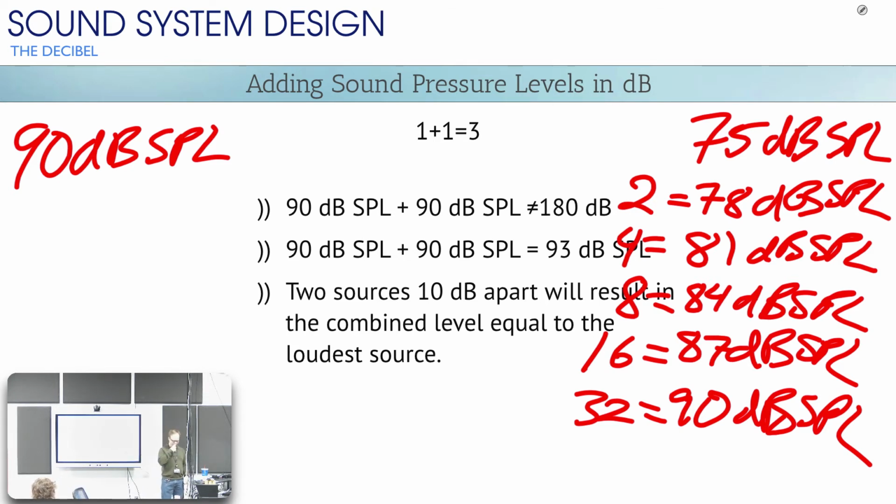Yeah? If you have a distorted signal and a clean signal at the same level, why is it always that the distorted signal still feels like it's a little bit louder? Is it because of the compression? No, because it has more harmonics. Okay. All right, so the higher frequencies are louder, because a distorted signal just creates high frequency harmonics. So it's not that the whole thing got a whole lot louder. It's like parts of it got louder. Gotcha.